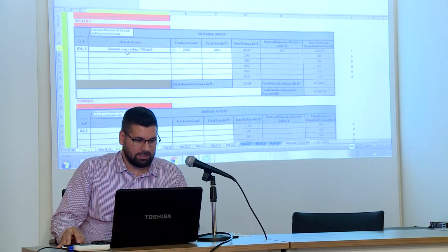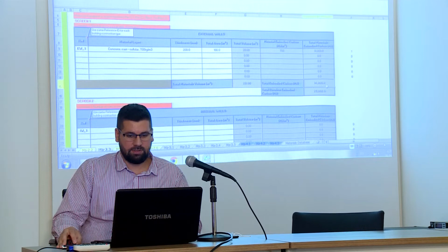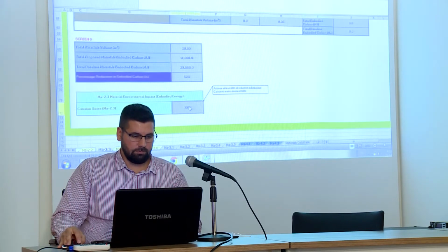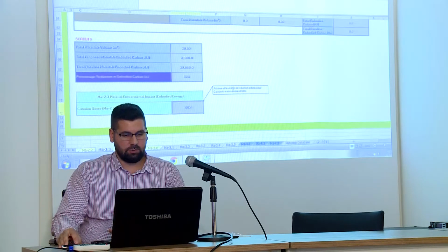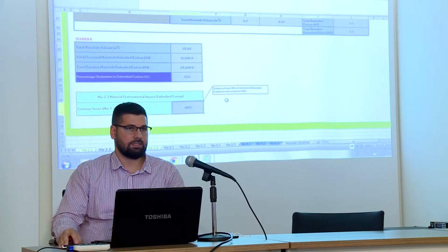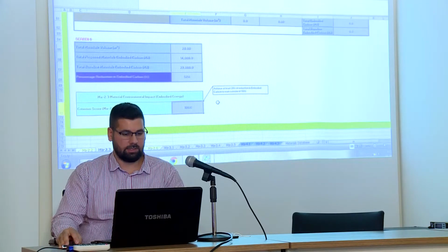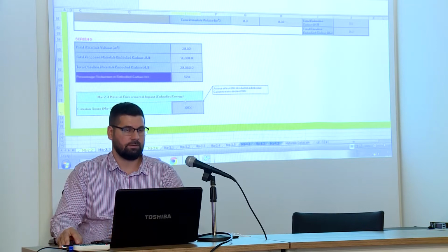Okay, so concrete cast cellular, which is a very lightweight material. The embodied carbon here is 14,000 compared to 29,000 for the baseline. And at the end, we can see the score is 100% because we achieve 20% reduction over the baseline. Okay, so whenever we achieve a reduction over the baseline, up to 20%, we reach a score of 100%. Clear? Okay.